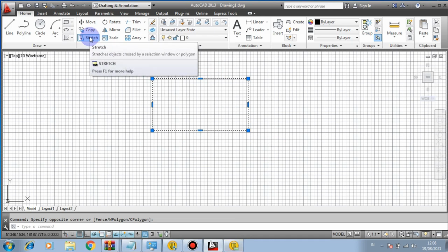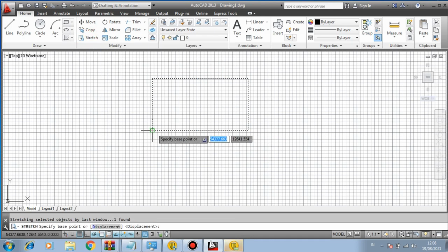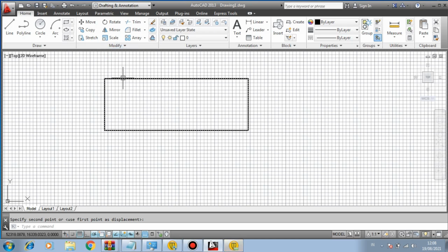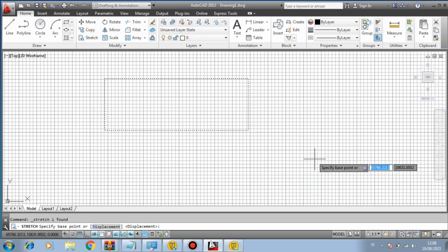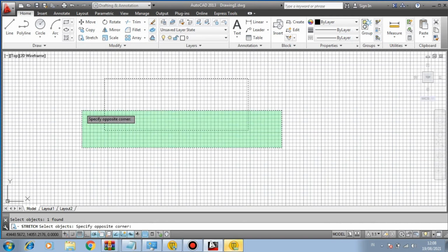Then stretch it. Click stretch, then click the left end here. Then pull it to the right. It will get longer. This applies whether you stretch it down to the right or upwards. Let me repeat. For example, I stretch it downward. First, click on the desired object to select it. Then click on the stretch function from the available options. After that, make sure to select the specific object you wish to modify. Finally, click on the block located at the bottom right of your screen in order to proceed with the operation.